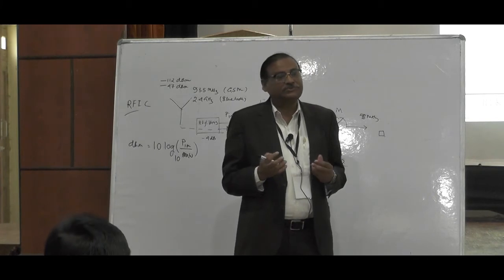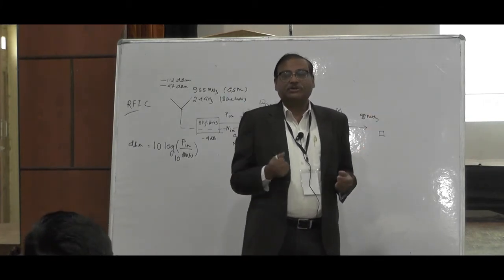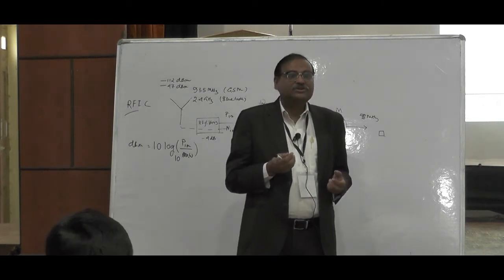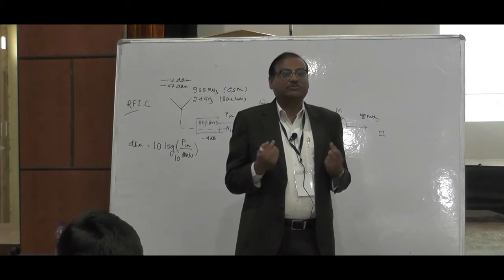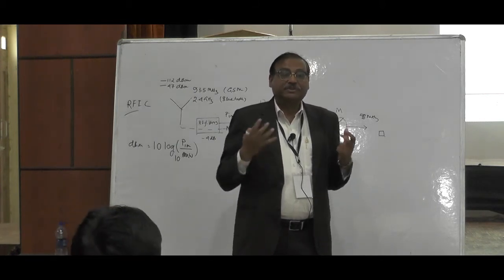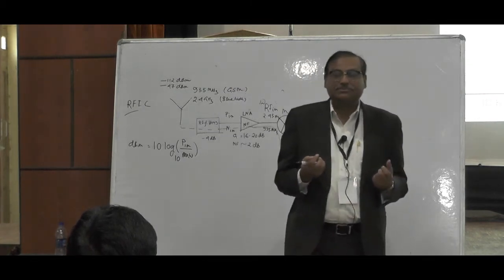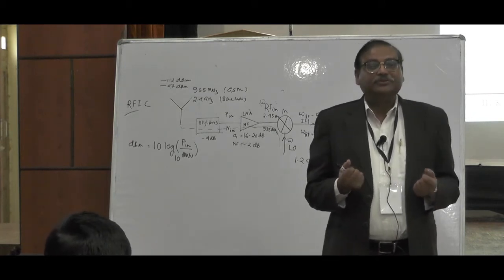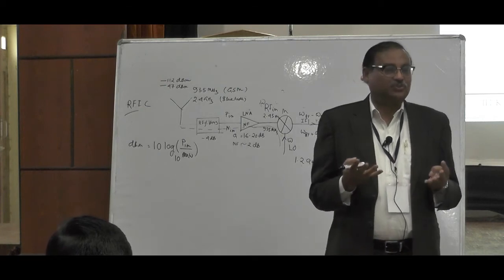Very low power consumption for sensor applications. Remote areas, I want to set up sensors with transceivers that should be able to run for 3 to 5 years. So typically the average power consumption should be in the sub-microwatt range, if not microwatt. So think of the challenge of today's wireless sensor nodes.